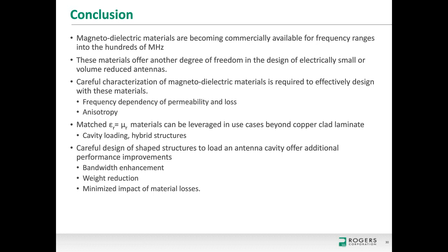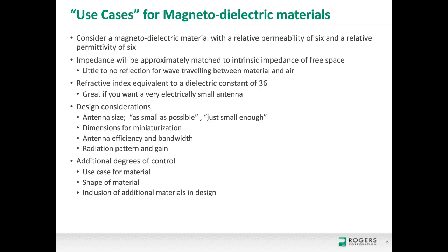Okay, great. Next question. Can we have an electrically small antenna, like 2 centimeter maximum at the frequency of, let's say, 300 megahertz, which is lambda over 50, and is referring to slide 15, which I'll push here? It may be possible to do something like that. I mean, if you do a patch antenna, you're starting with basically a half wavelength, and then you reduce that half wavelength by the effect of the magnetodielectric material.